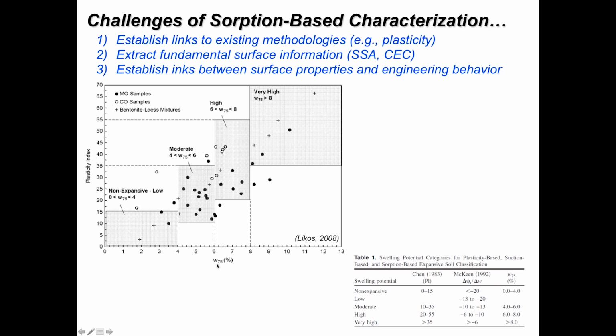This is from a measured sorption isotherm using water vapor: the gravimetric water content of, in this case, clay or a natural soil at 75% humidity. We specifically identified 75% humidity because that's the upper limit between water absorption that occurs for most soils as a short-ranged hydration mechanism, and at higher humidities, typically greater than 80-85%, where water starts to be absorbed under capillary mechanisms, which are sensitive